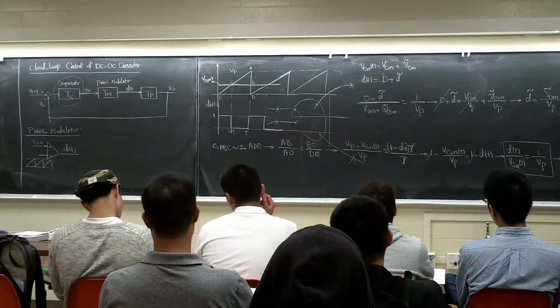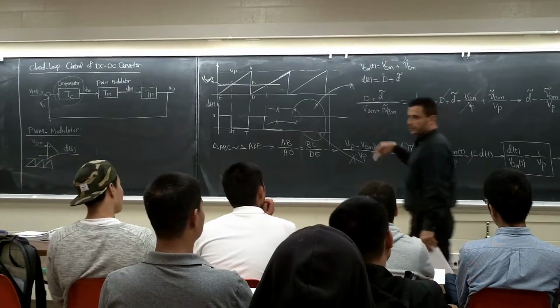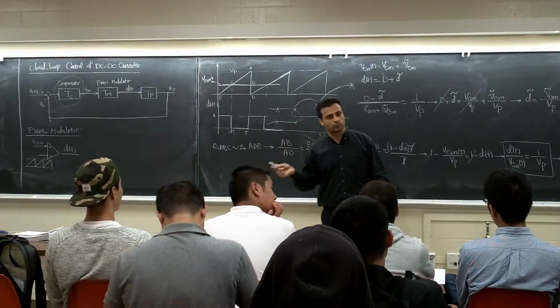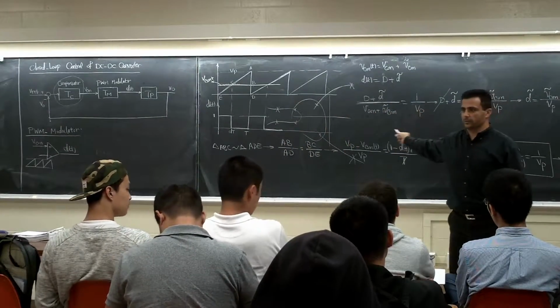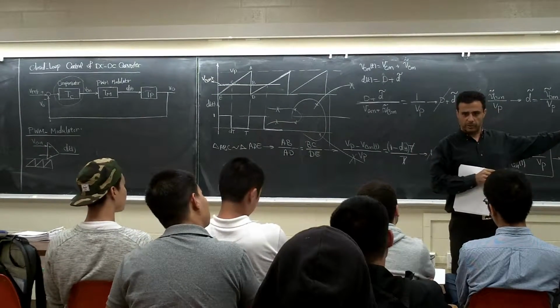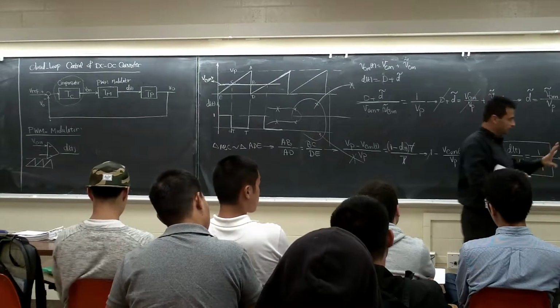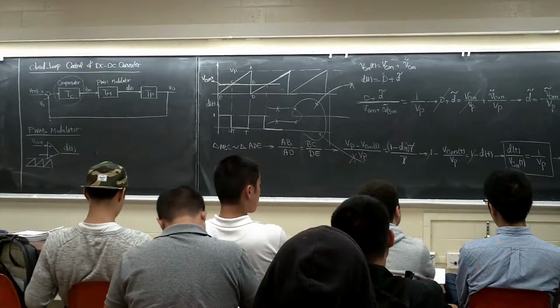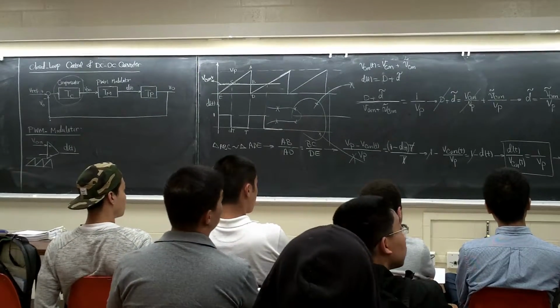But for those who are more advanced in control theory, there is nonlinear control, fuzzy control, adaptive control. There are lots of types of control you can use. But one simple one is this one: you use the Bode plot. Most power supplies are designed based on this. They use the Bode plot and design the control system. So, a quickie, we review the Bode plot, what it is, and what the phase margin is.